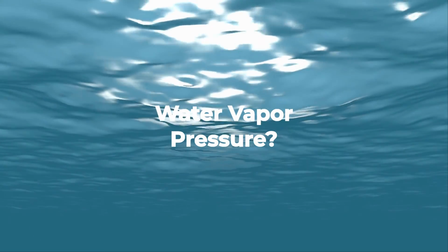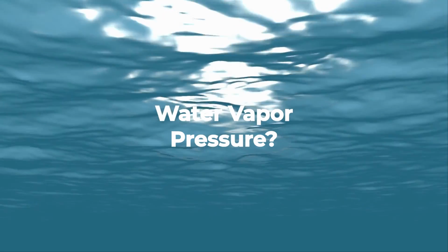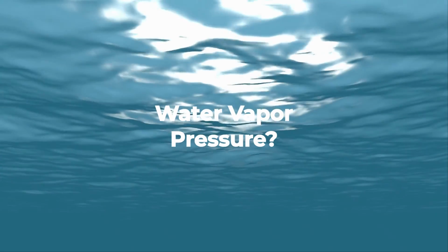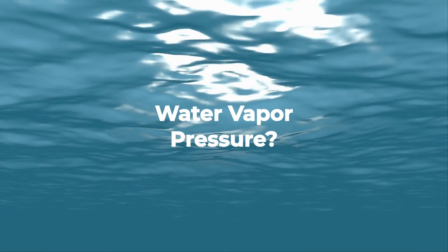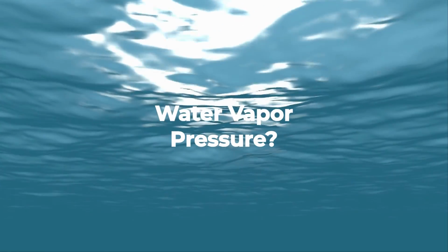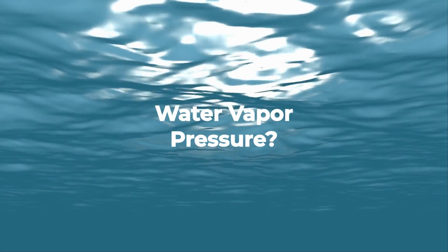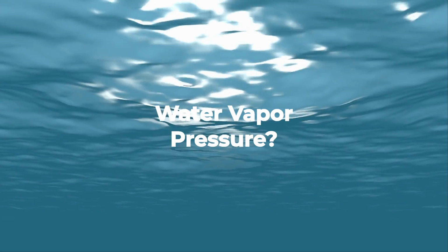Having a vapor pressure is very important because, as Jim said, in a vortex meter or Coriolis meter, if your line pressure and your vapor pressure and your pressure drop all kind of line up, your process could flash within the flow tube.